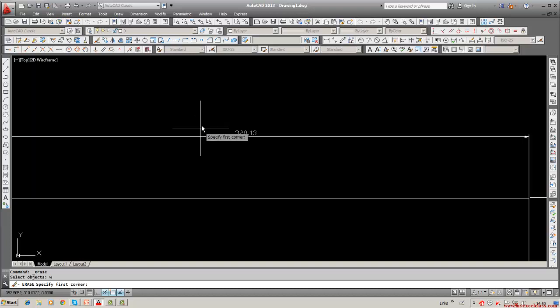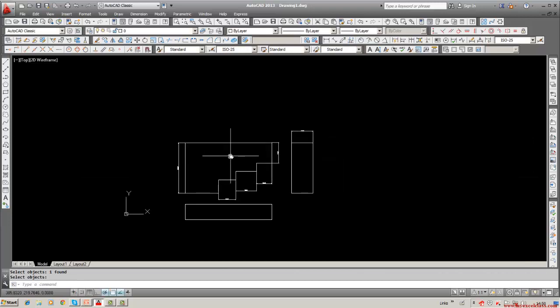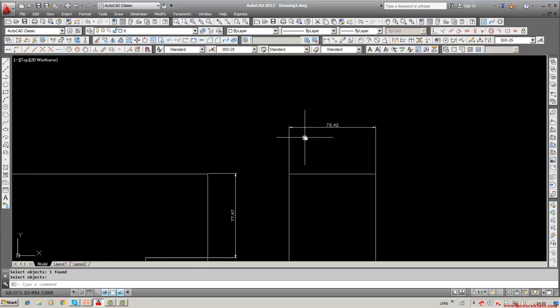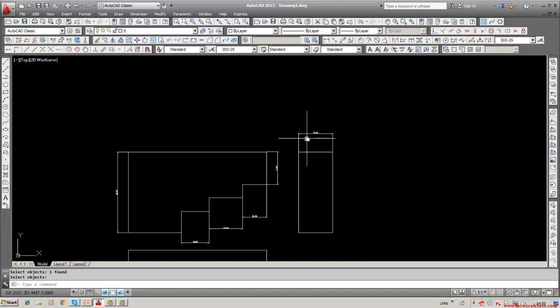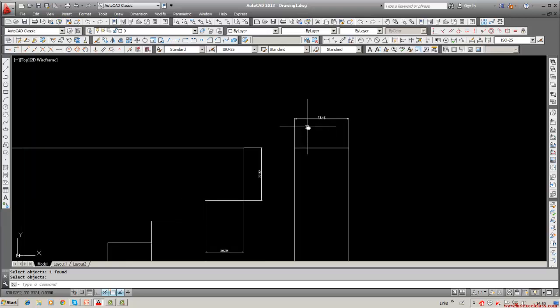So what you have to do is, if you want the size of the text matter to be equal to what you have actually indicated, you have to increase the size of the text matter by the scale factor, that is by 10. We have to increase by the reciprocal of the scale factor.